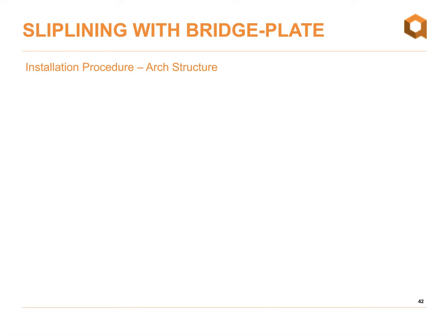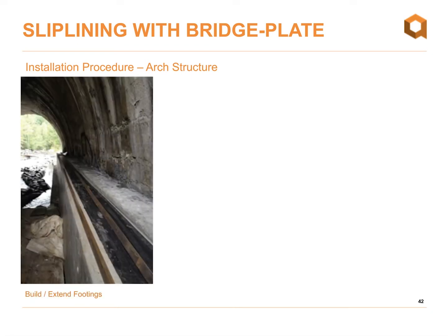Okay, so now I'll go through a quick installation procedure with an arch structure and just show how that varies compared to a structure with full periphery. Of course, we're dealing with footings, so we typically need to extend the footings out so that we allow for an area for the footing plates of the new bridge plate or multi-plate structure to sit within.